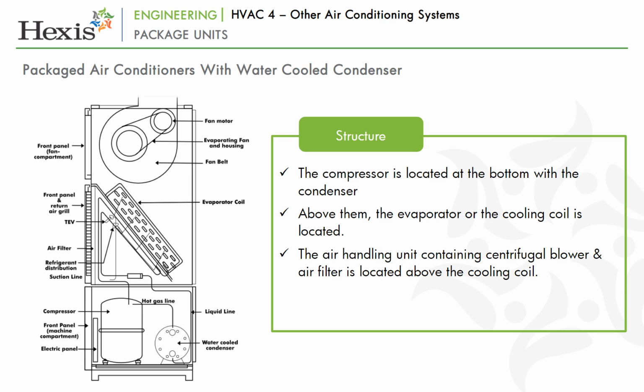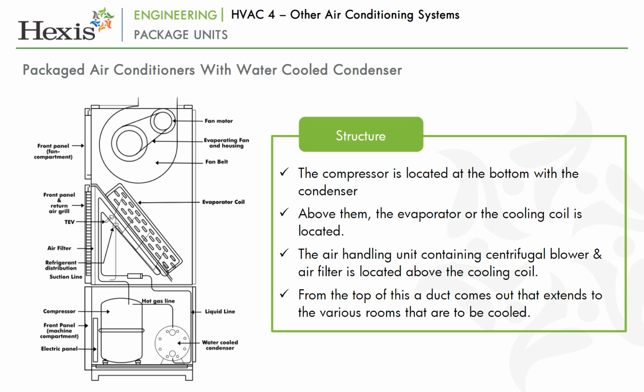The air handling unit comprising of the centrifugal blower and the air filter is located above the cooling coil. The centrifugal blower has the capacity to handle large volume of air required for cooling a number of rooms. From the top of the package air conditioners, the duct comes out that extends to the various rooms that are